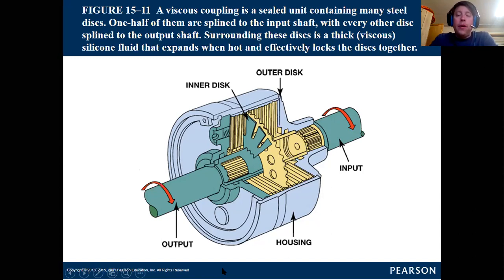And what a viscous coupling device, simply put, is a clutch pack component that has a fluid inside of it that is either electronically squeezed together or by fluid dynamics with heat, the fluid expands, thus squeezing the clutch packs together. So you're not really in all-wheel drive. You just have the ability to get into a various state of all-wheel drive.